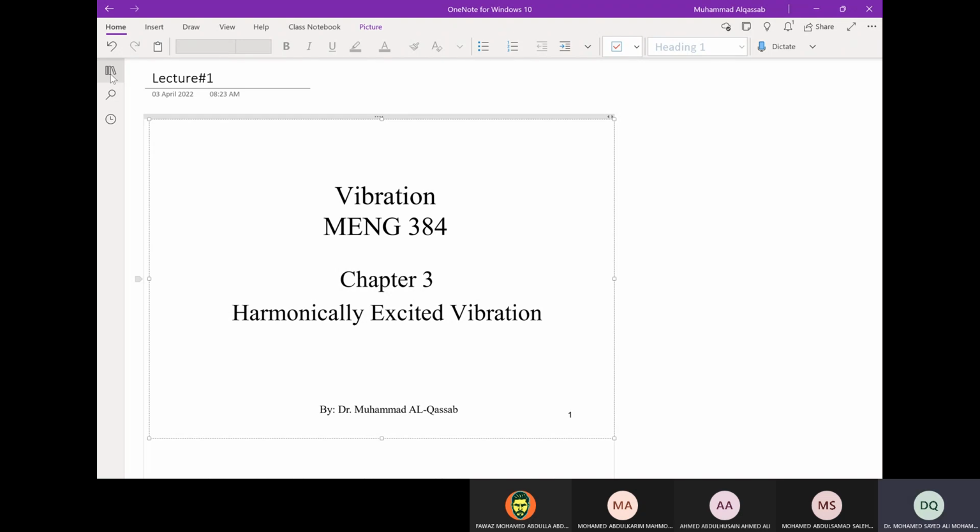The frequency of oscillation is either omega n for undamped, or omega n again for Coulomb damping. And it is omega d when we have underdamped, and omega d is 0 for overdamped and critically damped. So that's what we did.